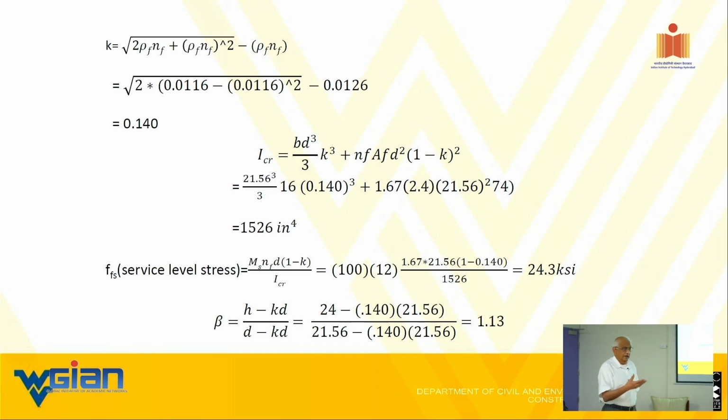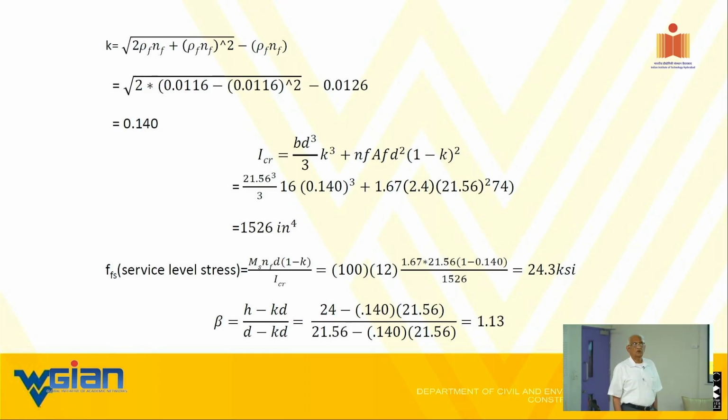It's a tension crack, so you are talking about 300 psi or 400 psi to tension failure. Naturally, concrete would crack. Under service loads also, we allow cracking, but we limit the crack. So what is the limit for the crack? That's what I gave you.